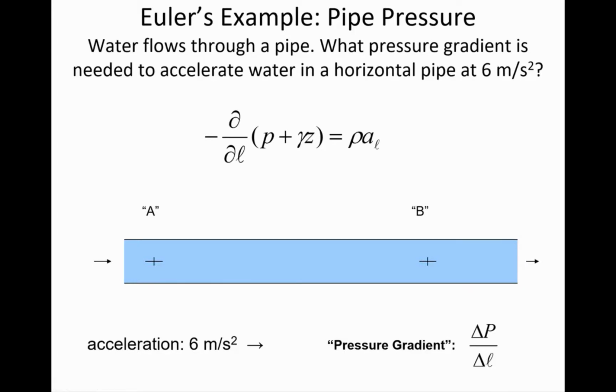But because it's accelerating with respect to time, the velocity 2 minutes from now will be higher than the velocity right now. I just wanted to start us off by differentiating between the convective acceleration and local acceleration. So this is local acceleration. If the acceleration is to the right, then the pressure increases in the opposite direction. So there's more pressure at A than there is at B.